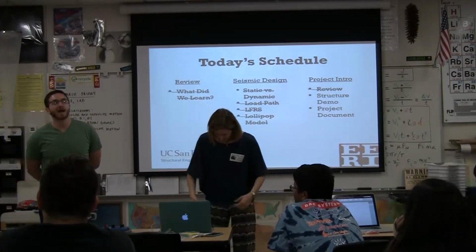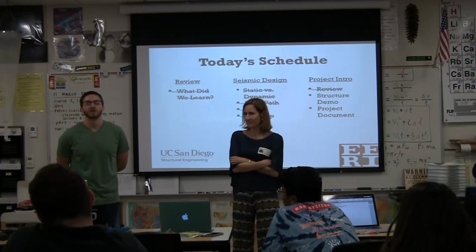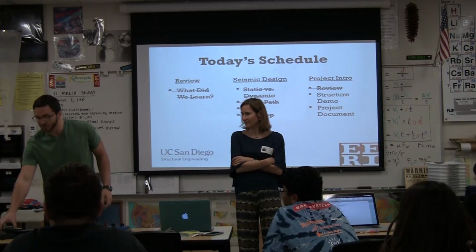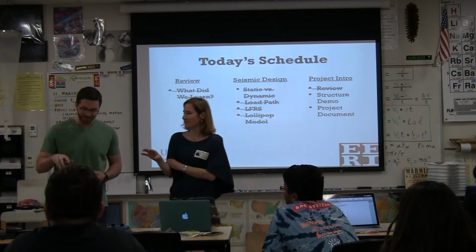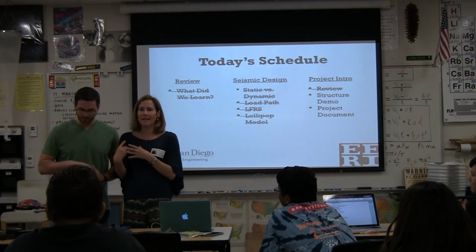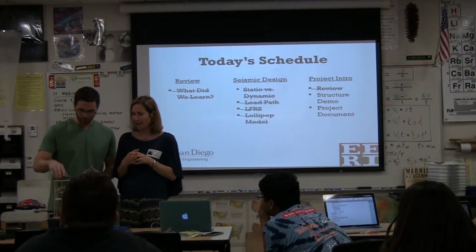Right? Moment frames have very specific connections, and we haven't done anything to reinforce these connections. So if this thing does not have an LFRS, what do we expect to happen when we shake it? It's going to fall. Yeah. So we're going to get into this project, but pay attention to this particular structure, okay?